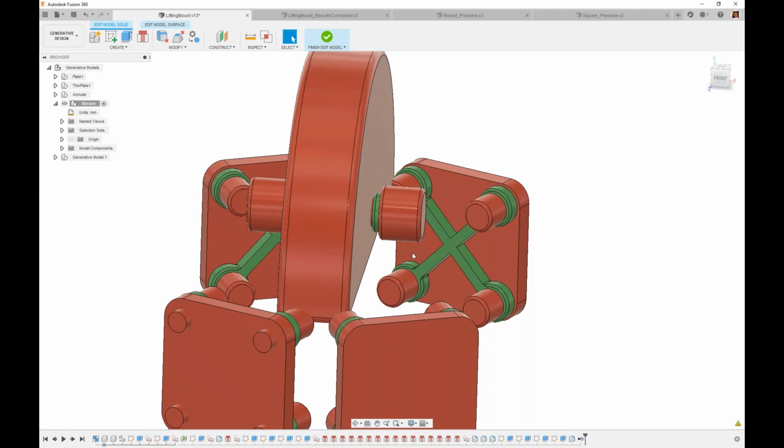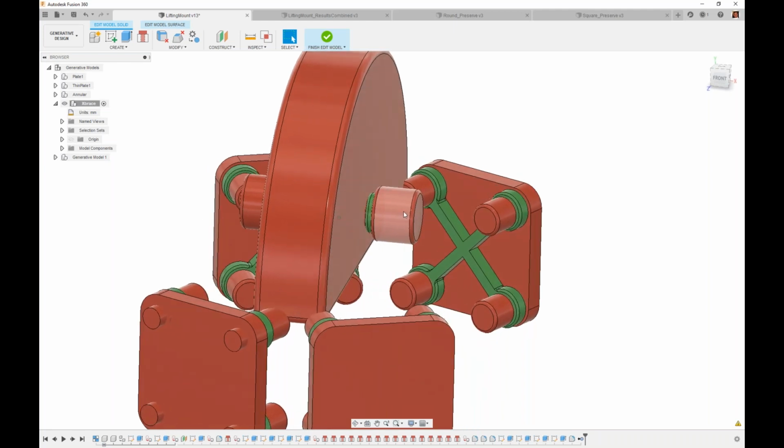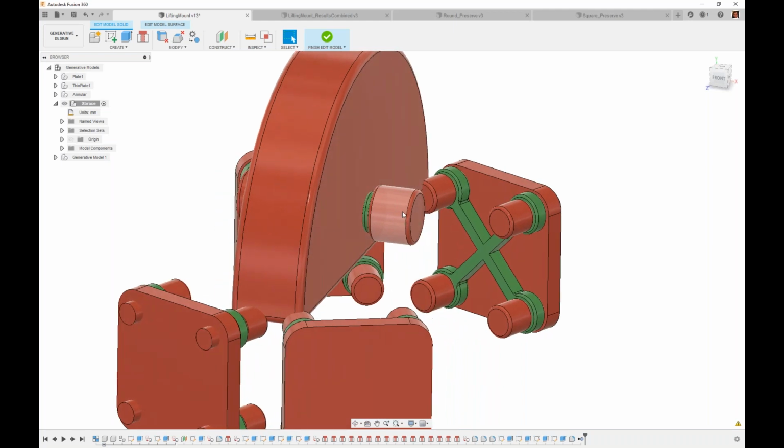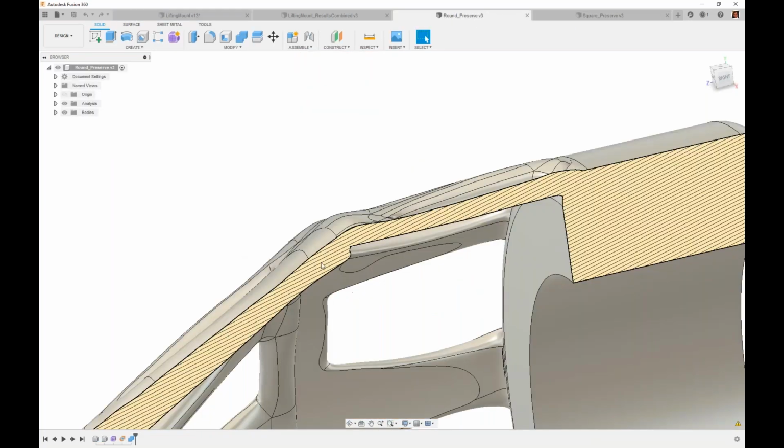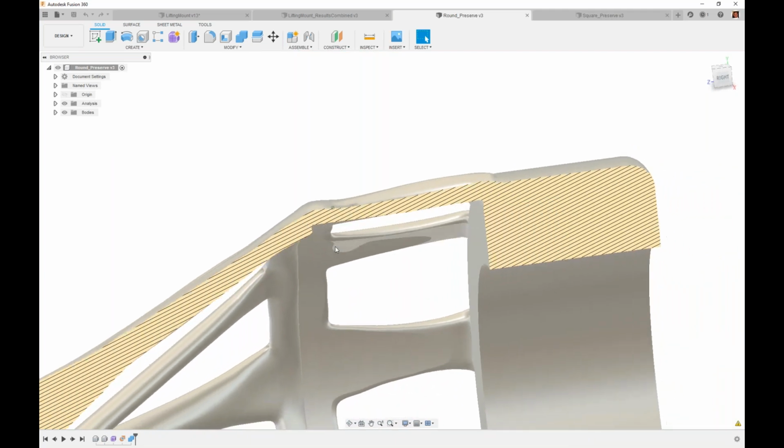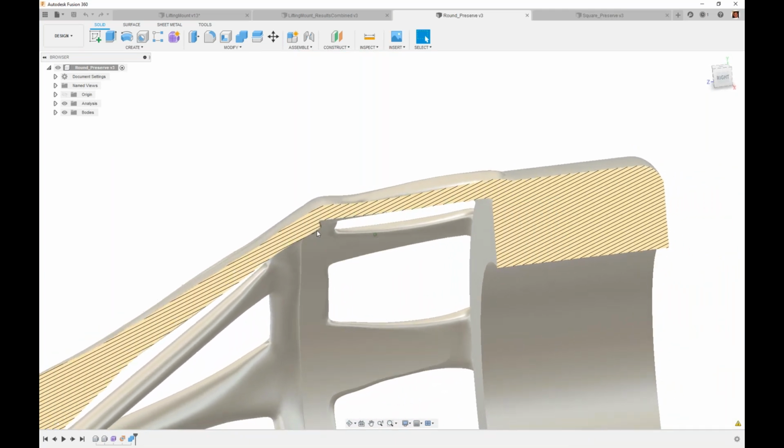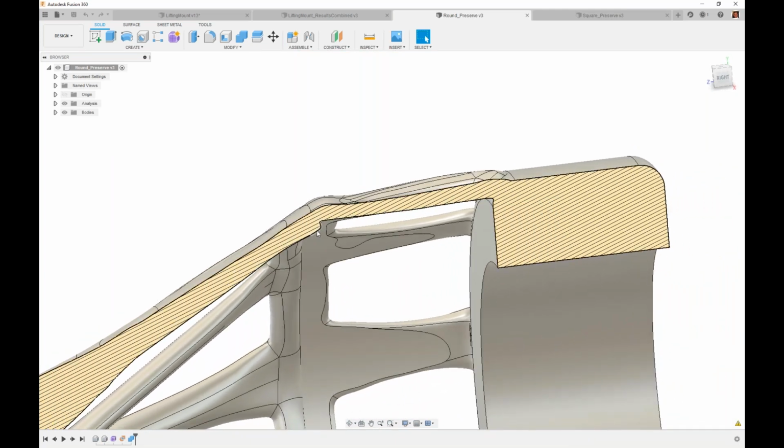So, for example, if this given bolt was a 25 millimeter bolt, I might actually make the obstacle region 26 millimeters. The reason for that comes back similarly to this here, in that we're going to try and butt up right to that obstacle region.